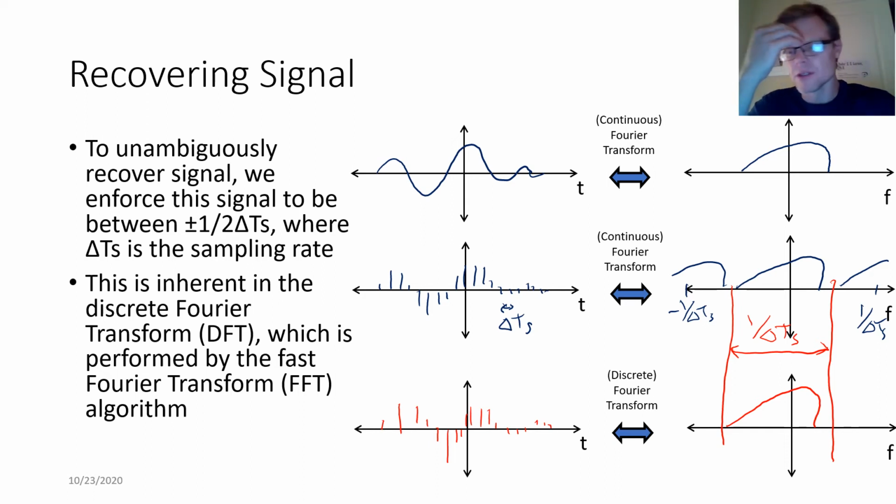Just to illustrate again, when we go ahead and do Fourier transforms on sampled signals, why don't we see a bunch of these repeated copies? That's because of how the discrete Fourier transform is defined. This signal in the middle row has an inherent repeating structure, so all you need to do is look at one copy of that to understand the whole signal. And that's the theory behind the discrete Fourier transform.